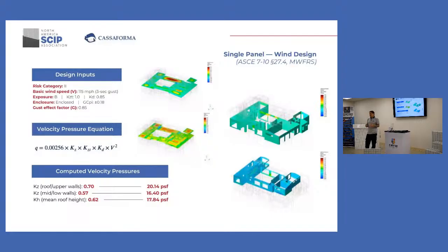That's why you can reach very high cantilevers. We have done cantilevers of about 15, or let's say 12 for sure, feet. That's because the lateral walls are also working as inverted beams, or as brackets. You have to understand that they work as a whole, and therefore you save a lot of reinforcing, and that's the goal we have in mind.